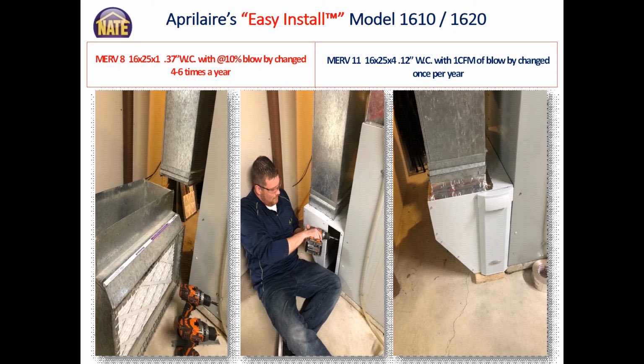And then you can see it's pretty straightforward just to secure it with foil tape. And of course we used a beta caulk on the attachment point from the cabinet to the 1610 air cleaner. That gives you now the ability to slide in a much wider pleated filter.